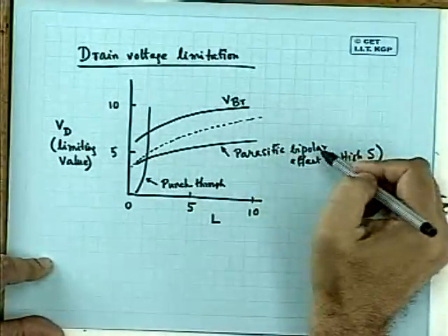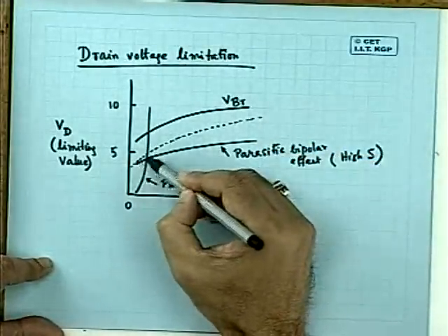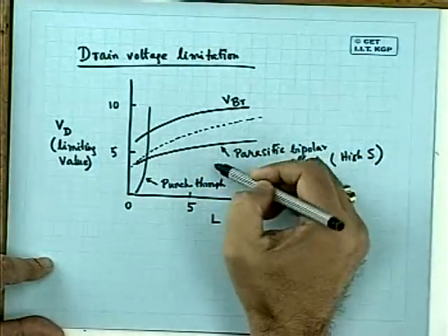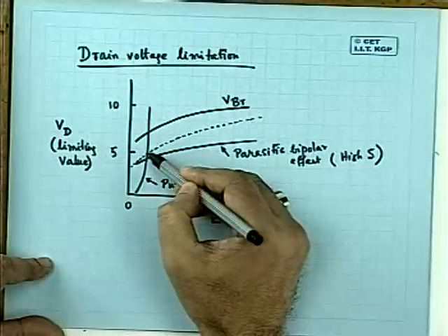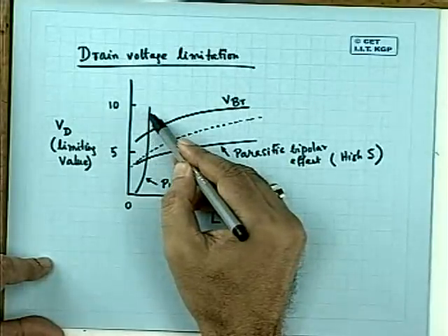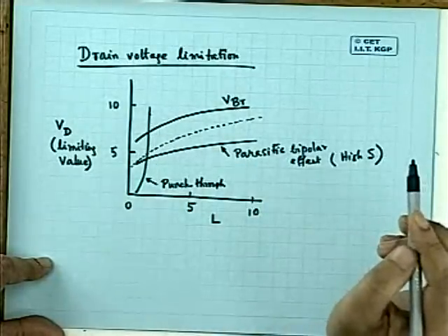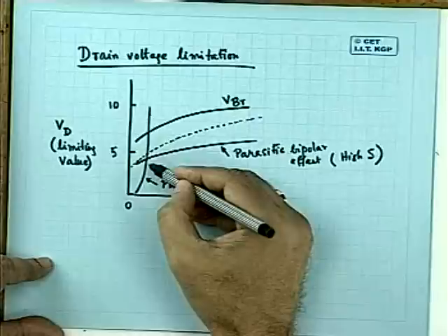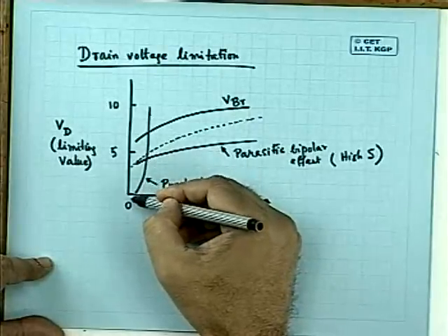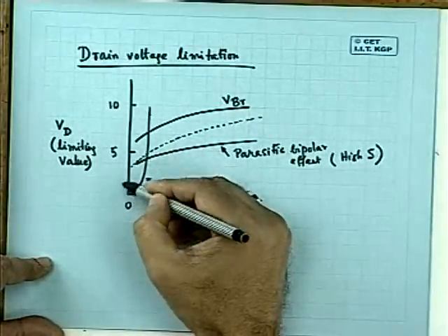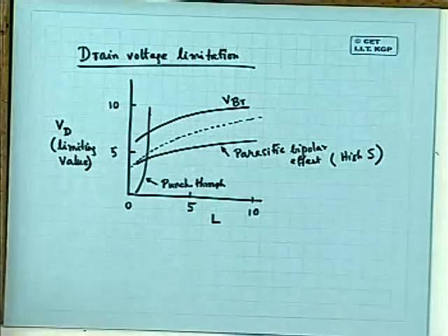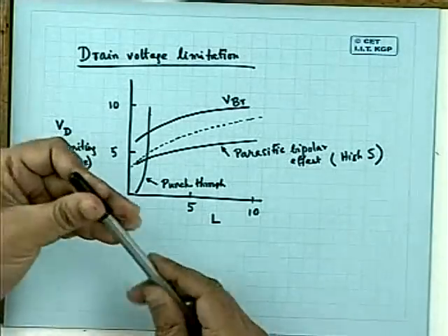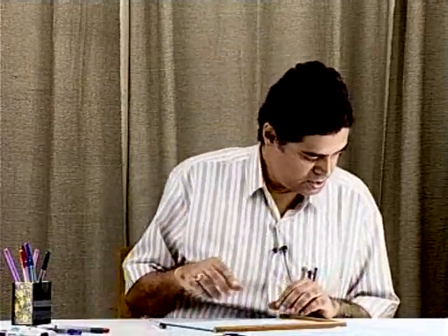Between VBR and the parasitic bipolar effect, you can draw a curve, and you should be below this. At the same time, because punch-through voltage was very high, you were not bothered earlier, but now the punch-through voltage starts falling. You should be limited, particularly in a region like this. So this is a very complicated picture, and that is why people do channel dual implant and various other things.